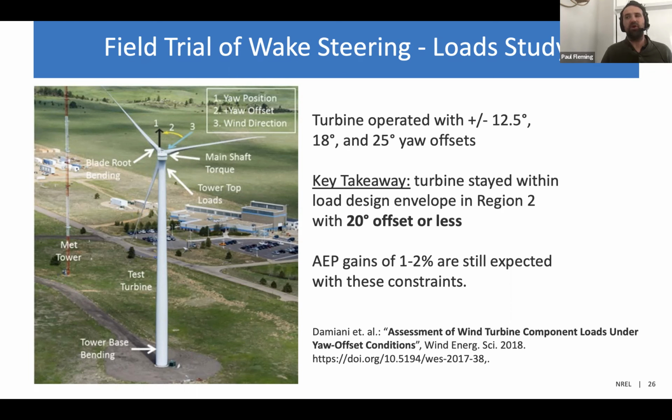But typically, once every turbine on the farm is fully rated, at least from an energy perspective, there's no advantage anymore, because any additional energy you send downstream, the pitch controller is just going to dump. So that's why we typically don't operate there. And then it just makes it a little bit easier to make the loads case. If you're not operating in really, really windy conditions, you don't have to consider what the loads impacts would be under those conditions.